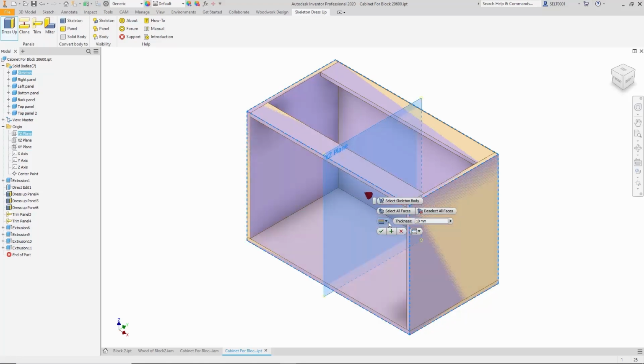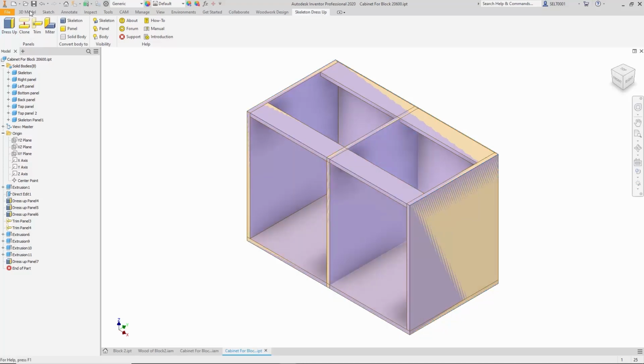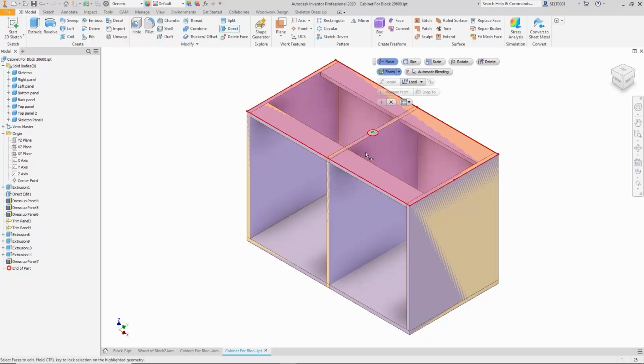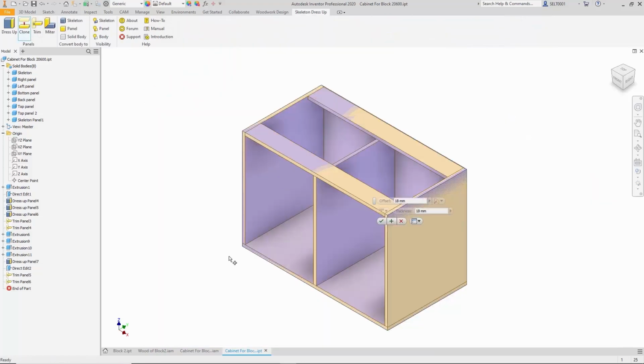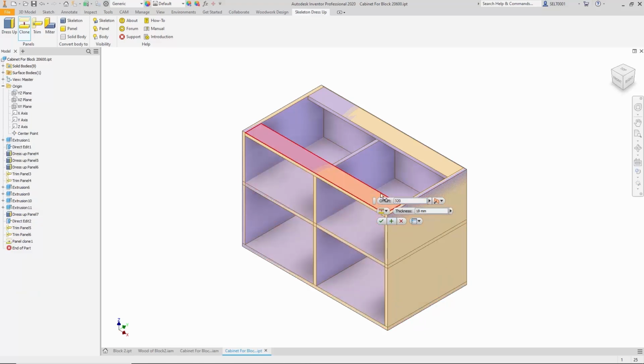and ask the system to add an 18mm panel through the central plane. That partition gets adjusted using the Direct tool. On one side, we had a shelf positioned at a height of 320mm. The shelf is then trimmed to fit the cabinet body in the reference guide.